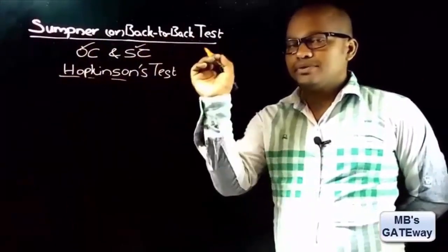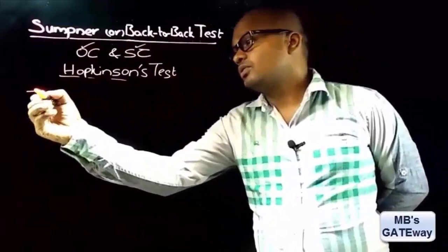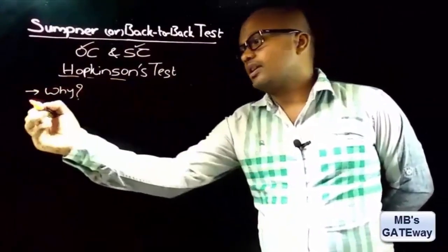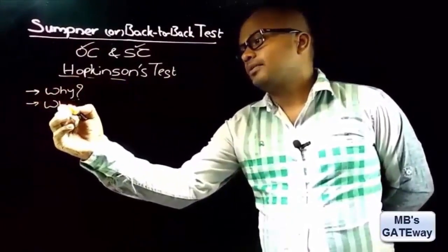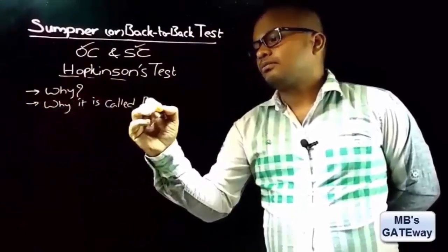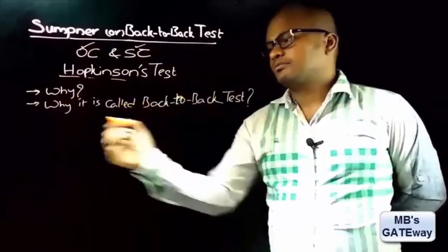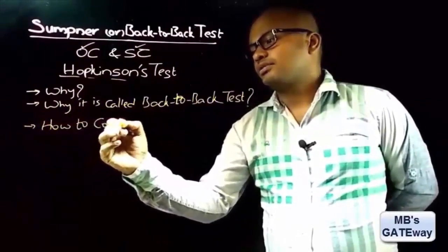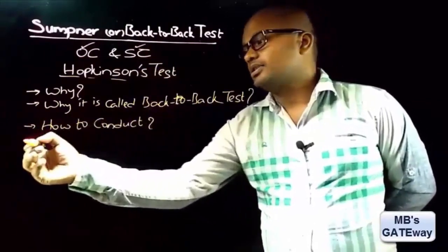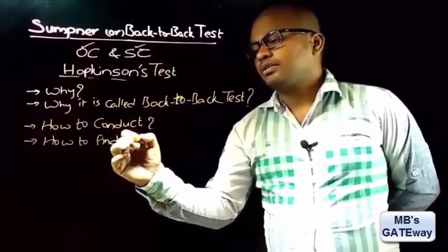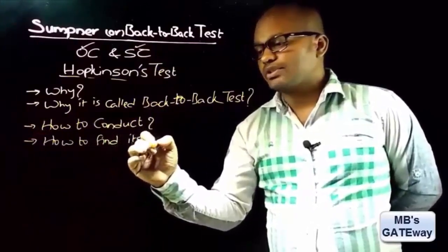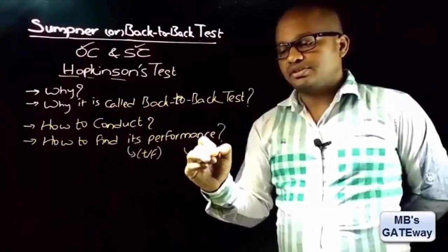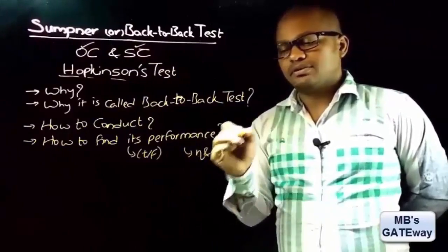And from this video on Sumpner's test, you will get to know why Sumpner's test is to be used and why it is called back-to-back test, and how to conduct this Sumpner's test, and how to find transformer performance, that is how to find the transformer efficiency and percentage regulation.